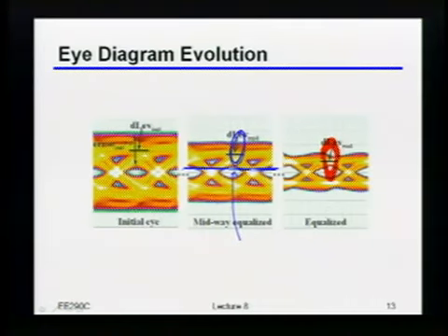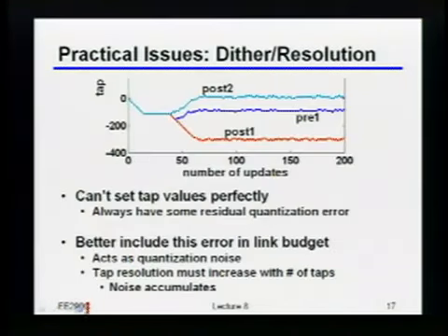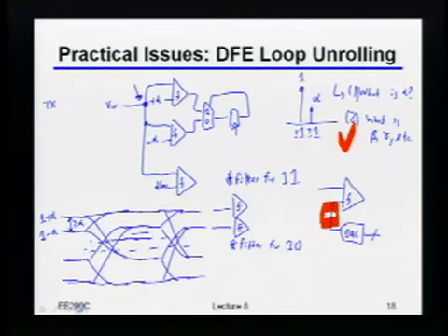So that's the problem, right? Because basically, I don't know what the real comparator threshold at this point is either. All I'm doing is assuming that there's some good mapping between what my data level is doing and where my comparator is actually sitting. But because I don't have a closed loop way of doing it, I can't actually enforce that.